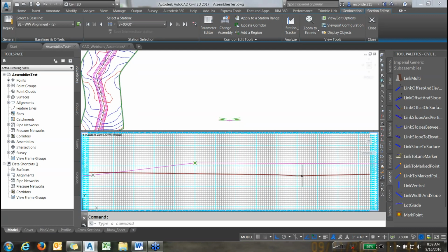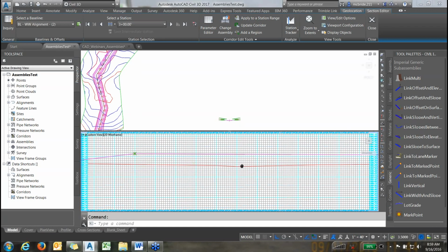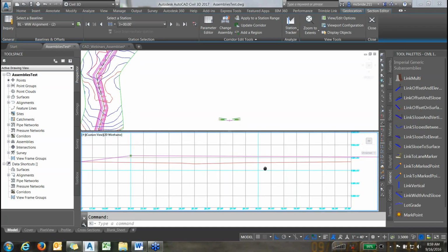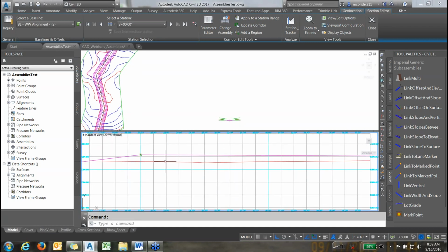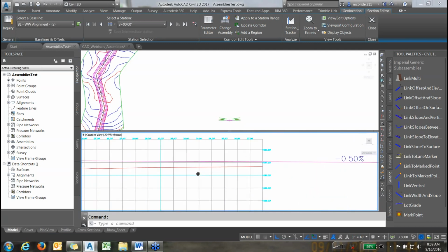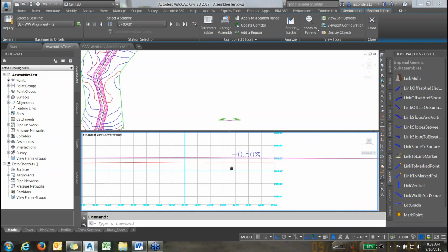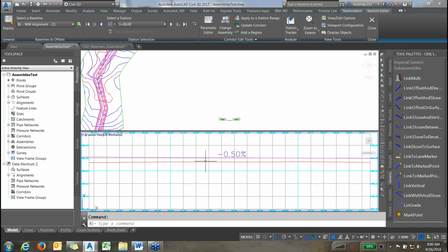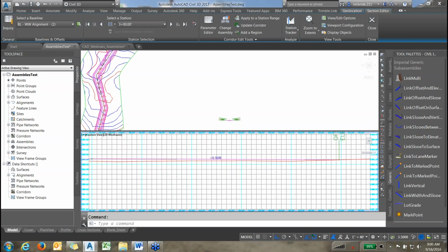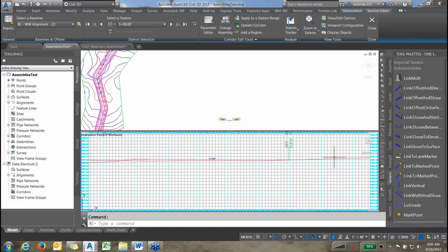Okay, so again, with the last one you guys were asking about, it would have just cut straight down here and no water could have got in from the right side. But as you can see, this ground line keeps going higher and higher and higher, and eventually, if I zoom out here, it does meet up with the existing ground, and so all the water is going to flow from the high ground down across the flatlands into the waterway. Okay, so that was the purpose of why I did the two slopes of 6-to-1 and 200-to-1.